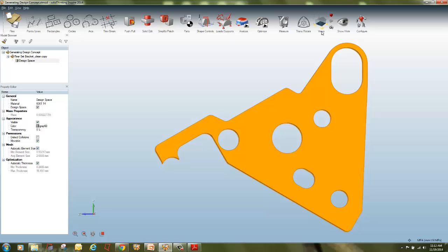To select the standard view, move the mouse cursor over the view icon in the main toolbar. As the cursor hovers over each face of the house, the principal face is highlighted and viewfinder lines are drawn above the face. As you can see here, this face, the back face, side, the other side, the bottom. So in this way you can change the view.